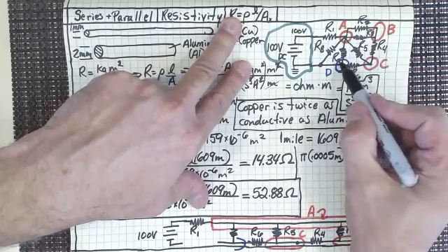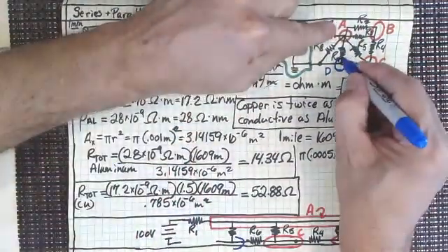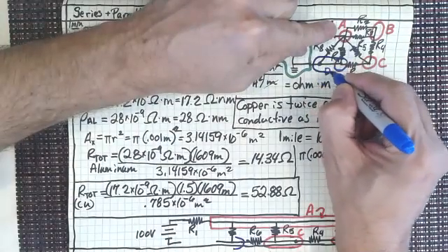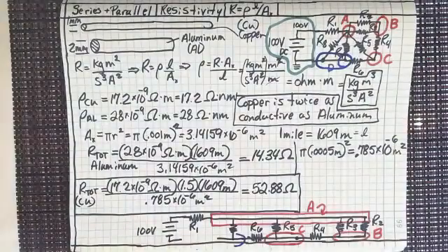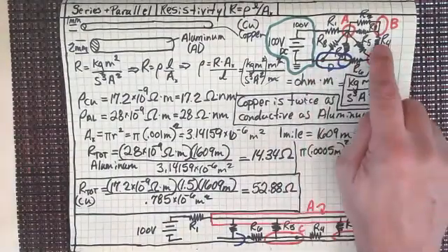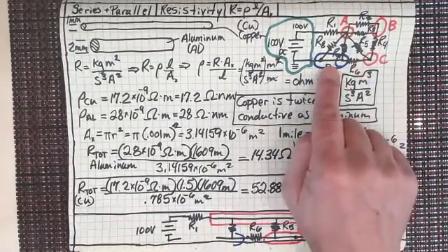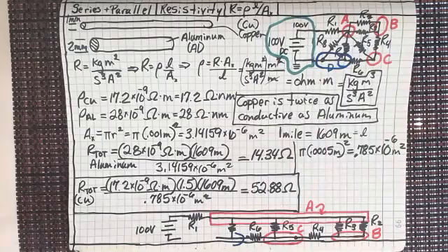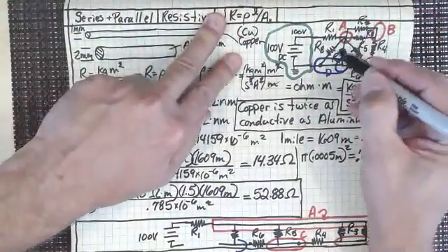And then, really, sorry that I just drew that there, because this node does extend over here. It's a short circuit, isn't it? So that whole thing is one node. It's all a short circuit there. There's no resistor there or anything. Like this resistor and this resistor separates those two nodes. There is no resistor there. So I'm just going to draw that. Those are all connected, A to D.